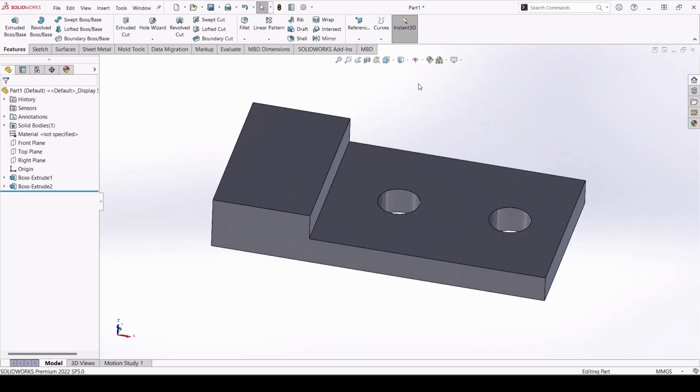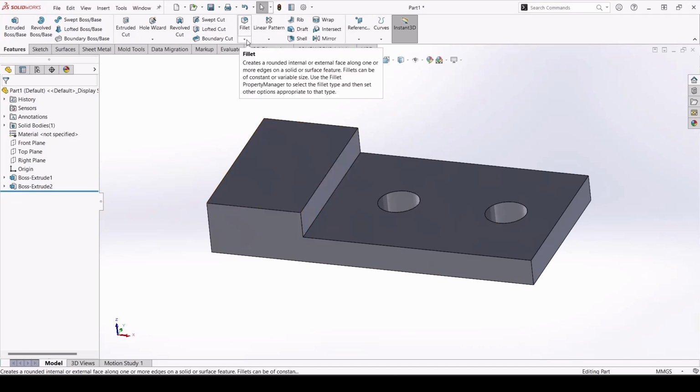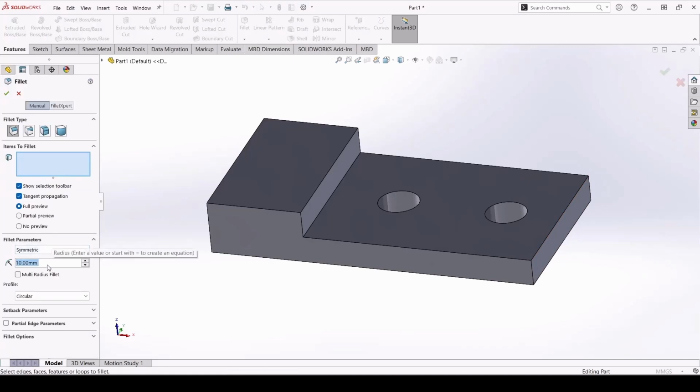All right. Now, we have extra features here. We have a fillet here and a fillet here, and 2 more fillets or 4 more fillets on this rectangle, but they're different, of course. So let's go ahead and create the very first fillets. So go to fillet, click on fillet, and then add in the dimension. So the dimension that we have here is 15.